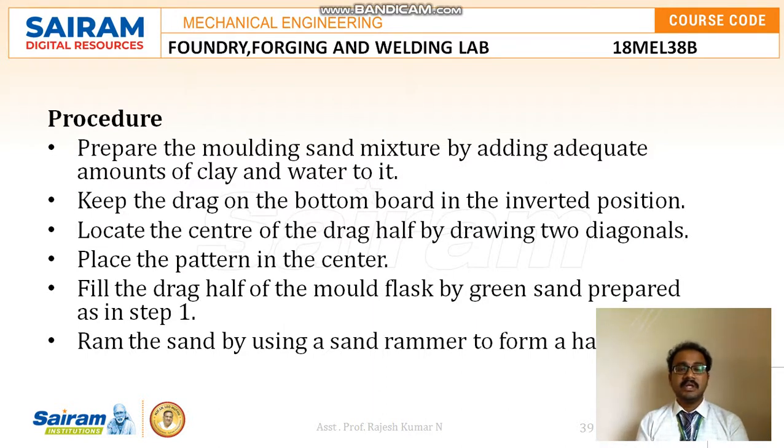So the step-by-step procedure should be followed for all the experiments except the pattern. There will not be any change in the procedure. We will see one by one. Very first thing is we have to prepare the molding sand mixture by adding an adequate amount of clay and water to it. As I said, apart from water we also have different liquid agents to make the required combinations sometimes. Once it is done, we need to keep the drag on the bottom board in the inverted position. We need to locate the center of the drag half by drawing two diagonals. So place the pattern in the center.